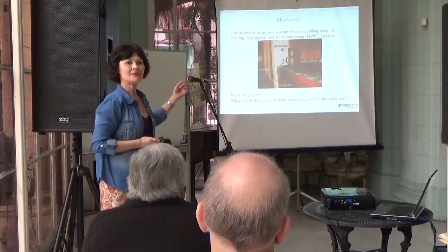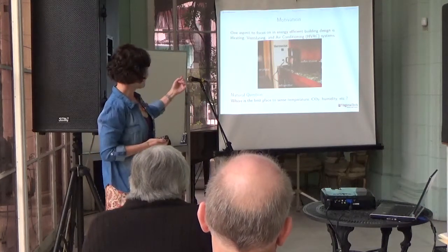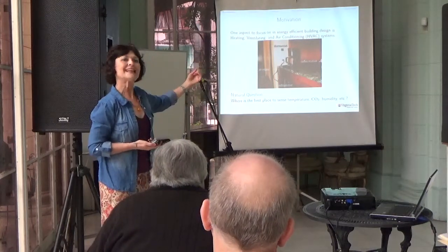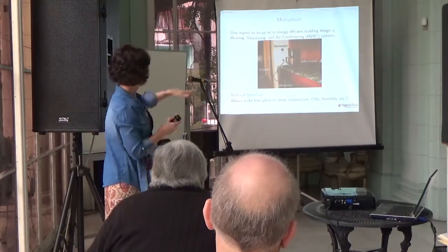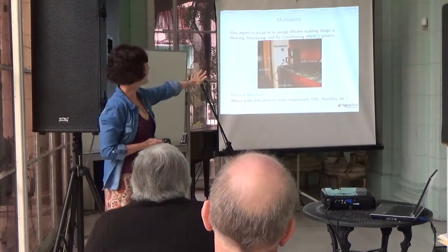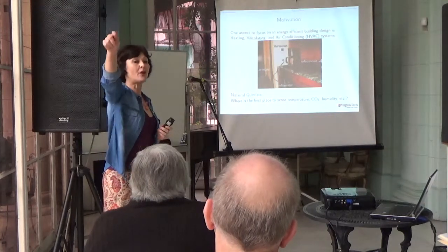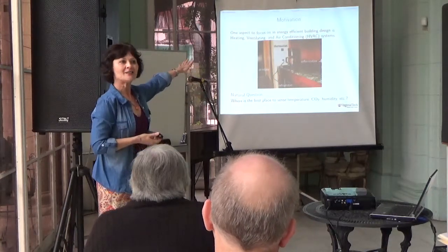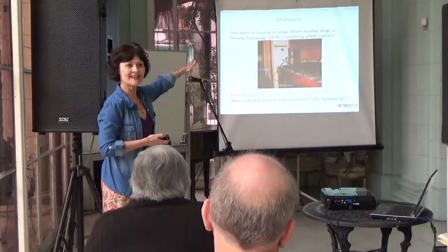So this is an example of not a smart place where the sensor is placed. There is a refrigerator that has heat that comes up. There is a coffee machine that makes it hot. And the air intake, how the air circulates, is right next to it. So what I can tell you about this room is that in the morning when you make your coffee, the air conditioning is blowing full blast because it doesn't know that where you are is freezing cold, because everything that it senses is hot. So the big question is, where do I place this one or two thermostats that I have?